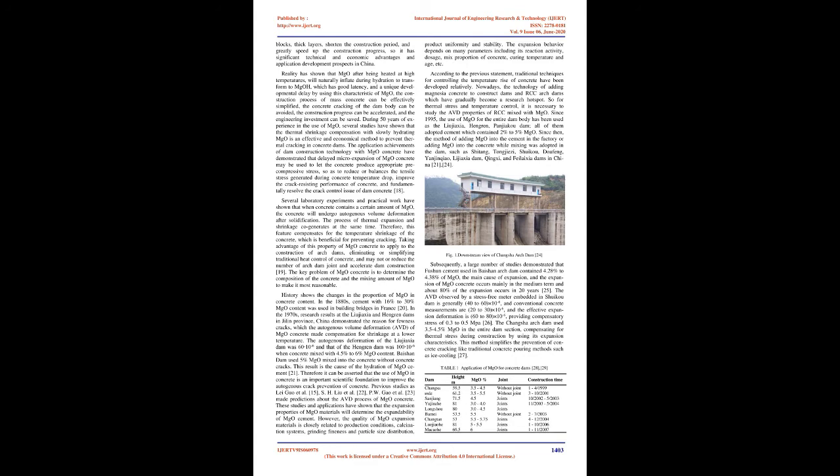The addition of magnesium oxide may cause expansion deformation. This approach was first developed in China in the 1970s when Chinese researchers and engineers discovered that the thermal shrinkage of mass concrete in the Baishan Dam was effectively compensated by the delayed expansion due to the slow hydration of the periclase contained in the cement clinker, and thus thermal shrinkage cracking was minimized. Then, Chinese researchers and engineers focused on the research of the hydration and expansion of MgO containing expansive cement.